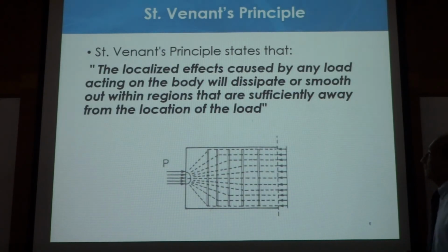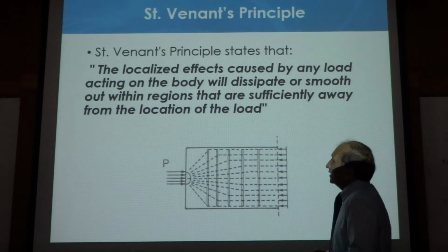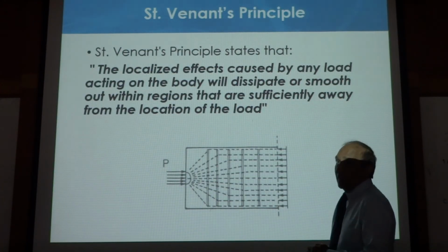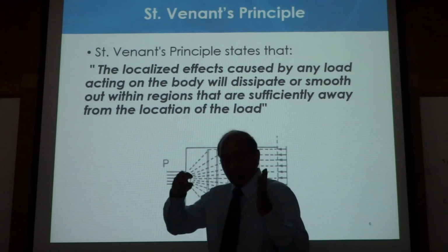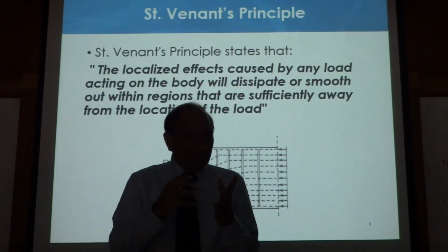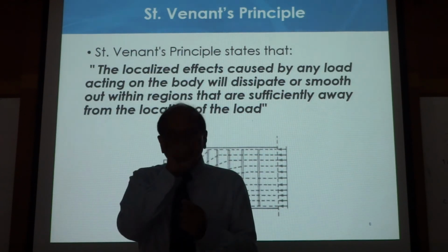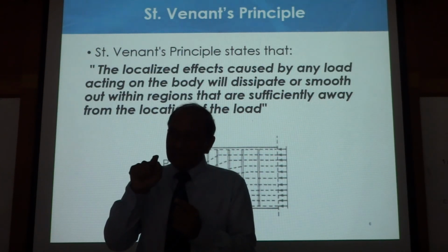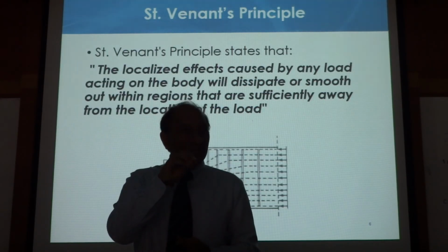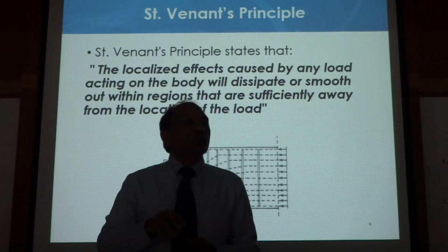Then we also have another theory, Saint-Venant's principle. This says that if you disturb a continuum with a localized force, the effect of that disturbance will fade away after some time. So those disturbances do not go too far.